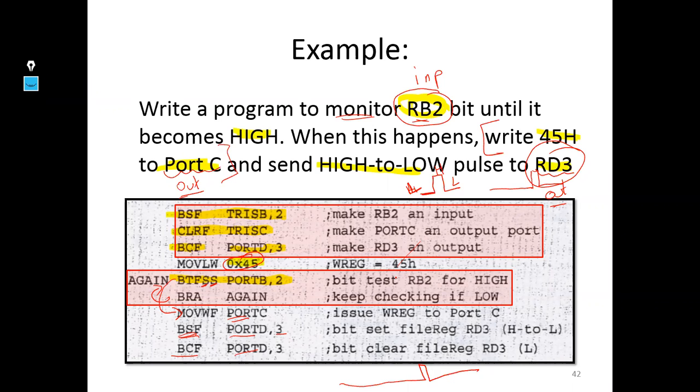The difference is in the input. If you are connecting, for example, a capacitor on the bit, or for example you have a touch screen, you want to connect this bit to the touch screen, if you have capacitive load or inductive load and you send the value to the bit and then you want to read the value from the bit, in that case it is better to read from the latch. But if you want to switch on, you can use either the port or the latch. It doesn't matter.